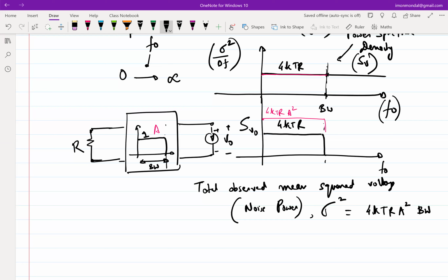So narrow band is when BW is low, wideband is when bandwidth is high. If I take corner cases, say audio bandwidth is 10 kilohertz, or 20 kilohertz. Video, the bandwidth is 20 megahertz. So basically 1,000 times higher than the other.